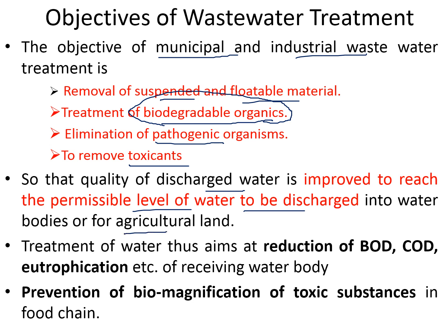So it has to fulfill certain requirements, and as per those standards you have to treat that wastewater. Generally the BOD level has to be brought down to 20 milligram per liter, and the COD level has to be brought down to 100 milligram per liter as per our Indian standards.